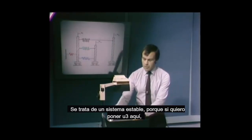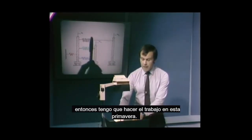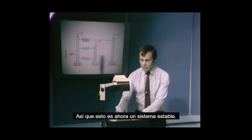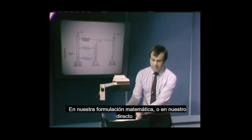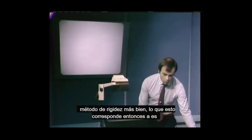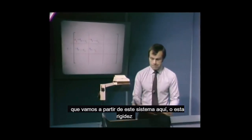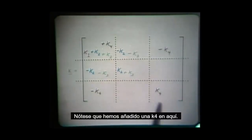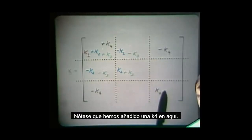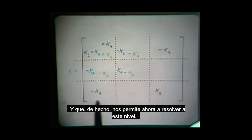It is a stable system because if I want to pull U3 over here, then I have to do work on this spring. So this is now a stable system. In our mathematical formulation, or in our direct stiffness method rather, what this then corresponds to is that we're going from this system here, or this stiffness matrix, to that stiffness matrix. Notice we have added a K4 into here, and that in fact allows us now to solve at this level.